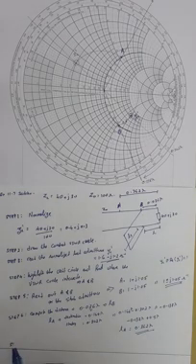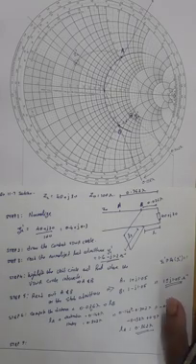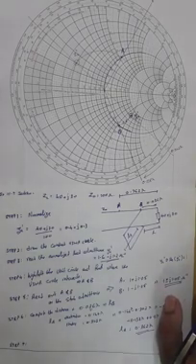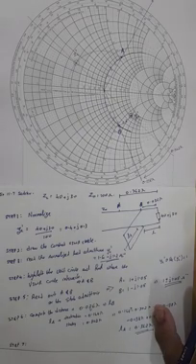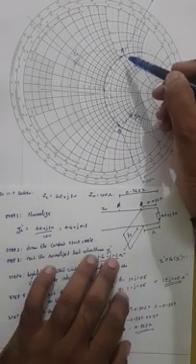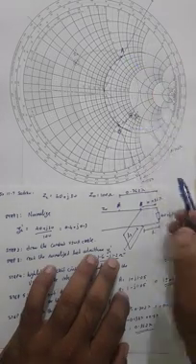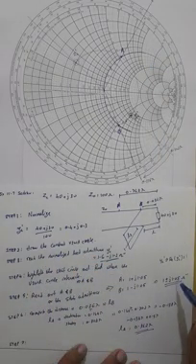Step 7. Now going back to the theory, if you remember, to find the length of the stub, you had to go ahead and compute the imaginary part. And to compute the imaginary part, one of the things we did was to multiply the numerator and the denominator with the complex conjugate. So that is what we'll have to do over here. You'll have to find the complex conjugates of point A and B. Now the imaginary part of point A and B happens to be at 1.05.